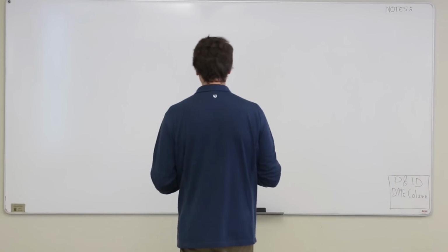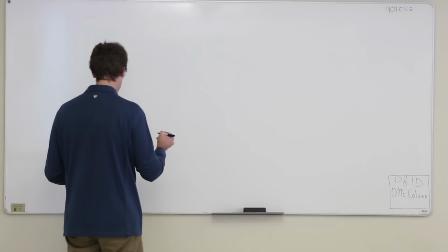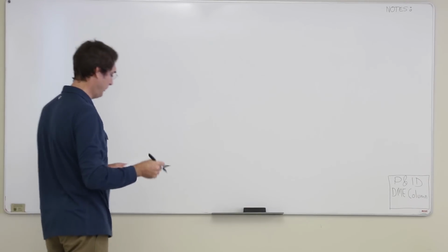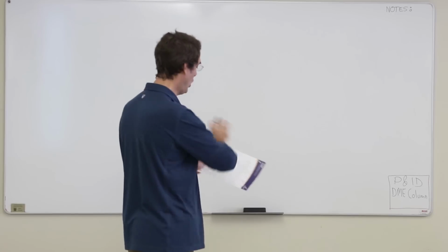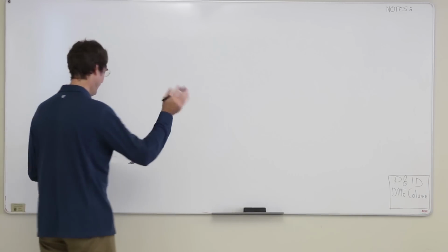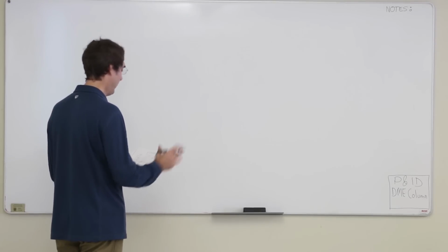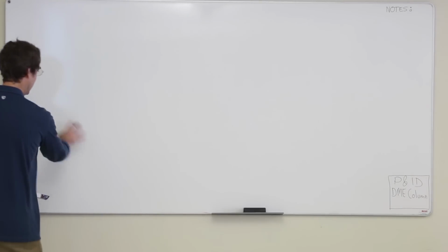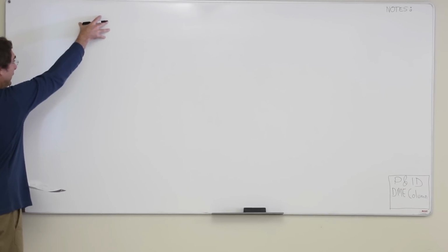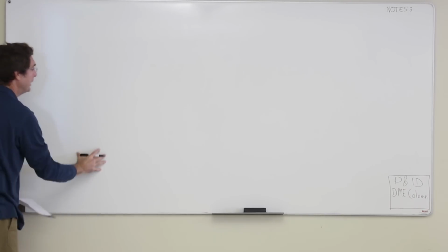So first thing to do is to get the tower itself drawn on the P&ID. And I know basically all my equipment is on the right-hand side of this P&ID, the condenser, the reflux drum, and the pumps, and all that good stuff. And then I'm just going to have the controls for the reboiler down in here. So I'm going to basically put the column right in here.